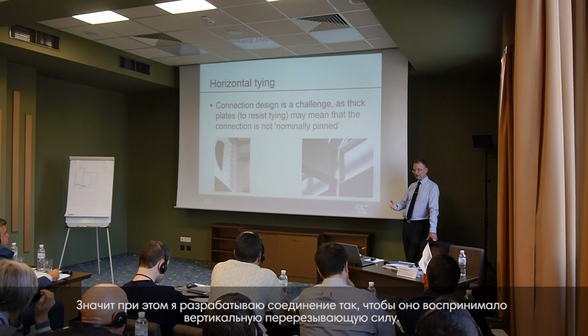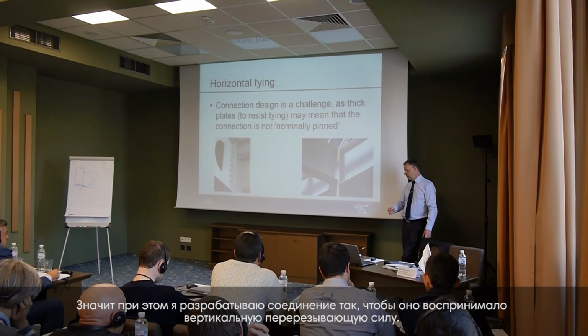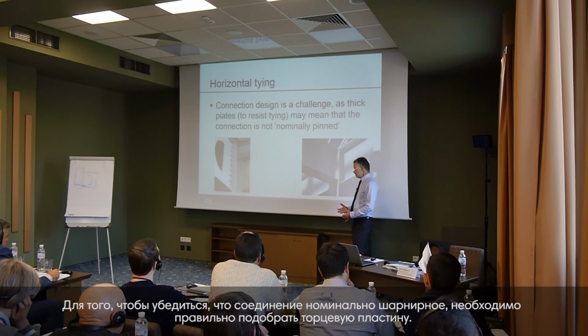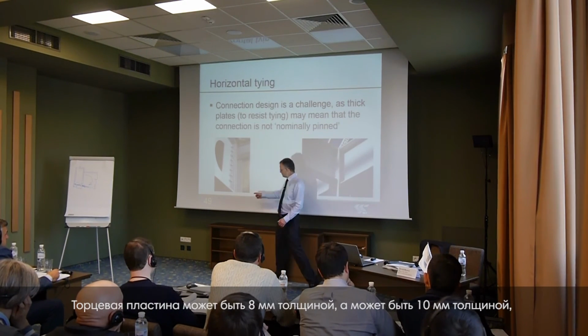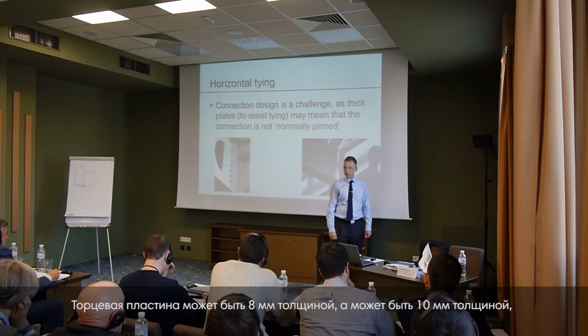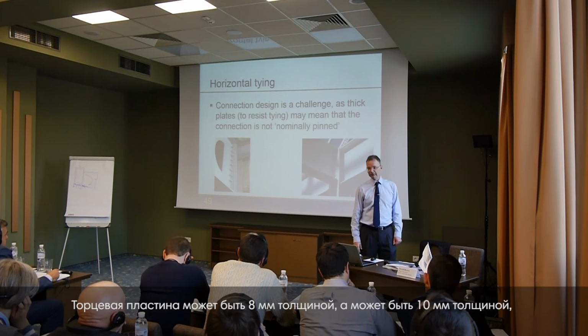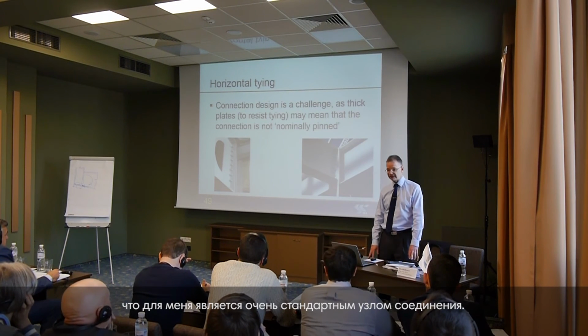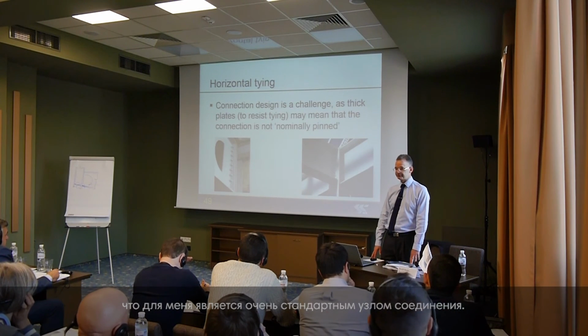I can design the connection to carry the vertical shear, no problem. To make sure it is nominally pinned, perhaps my end plates might be 8 millimeters thick, or maybe 10 millimeters thick. That would be a very standard connection detail for me.